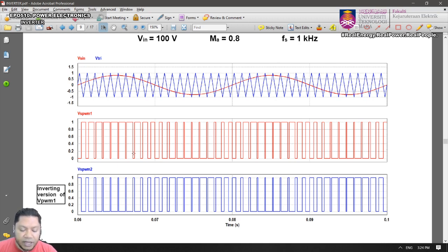will be connected to S2 and S3. So here you're going to have S1 and S4, and this will be connected to S2 and S3, right? So again, similar output voltage. Whenever S1 and S4 are on, the output will be connected to the positive E, or positive Vin. Okay, whenever S2 and S3 are on, it will be connected to the negative E, which is negative Vin. Just that.